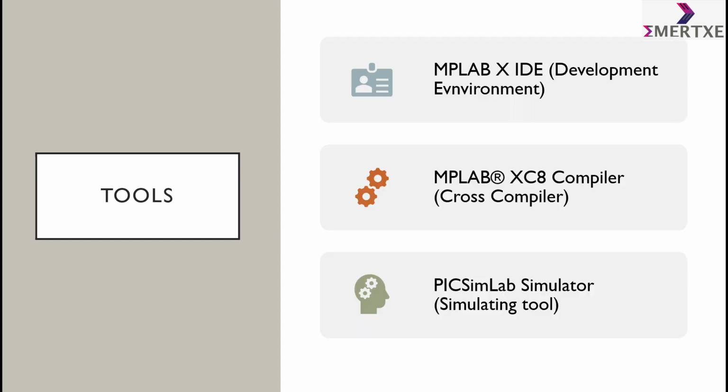The tool that we used in this internship is MPLAB X IDE, where we coded all the PIC microcontroller code, basically embedded C. We coded the program that we have to put in the microcontroller in MPLAB X IDE. The compiler that we used in that is XC8.